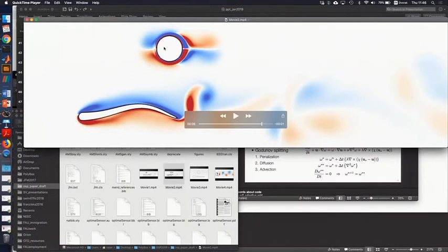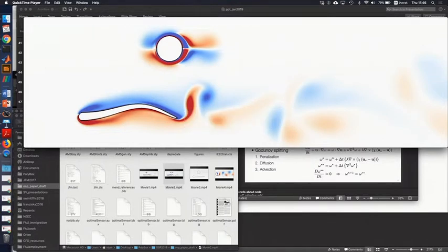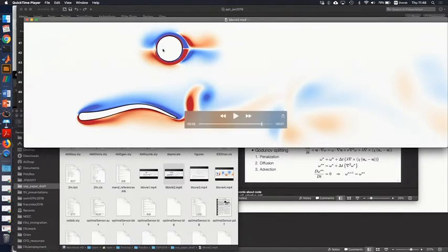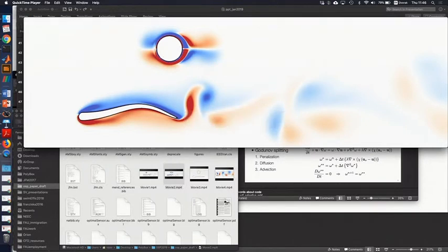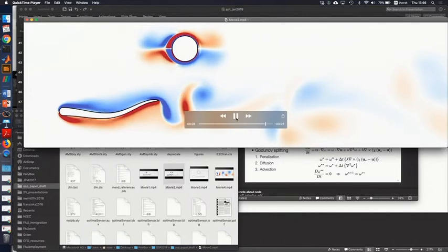by chi equal 1 and u solid equal what I impose. So what I impose is these grid nodes have a sinusoidal velocity, all of them. And in time, my patch, the green patch, moves. So new grid cells will be occupied by the solid. As it moves, it comes back. Older grid cells will be occupied by the solid, and that's exactly what happens.